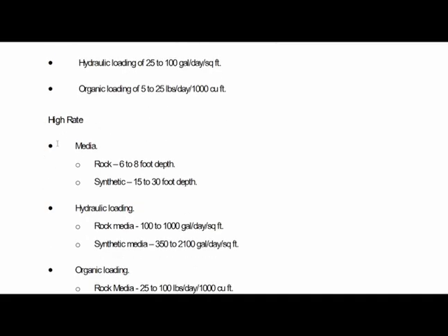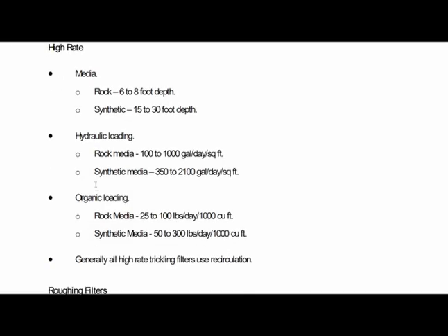High rate: the media is rock, 6 to 8 feet deep. Synthetic, 15 to 30 feet deep. Hydraulic loading is 100 to 1,000 gallons a day per square foot, and synthetic is 350 to 2,100 gallons per day per square foot.